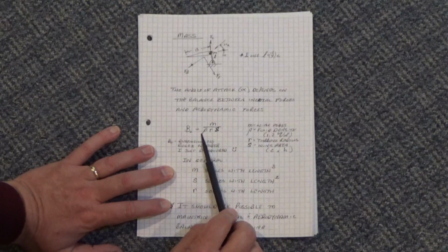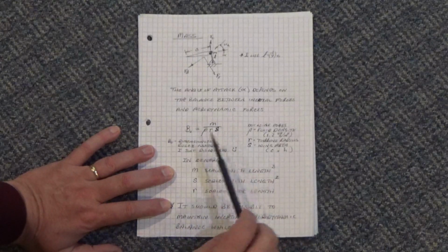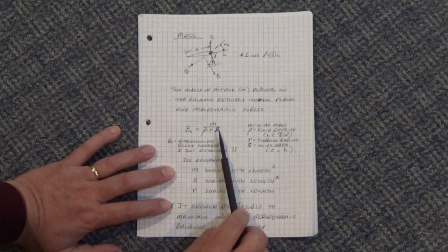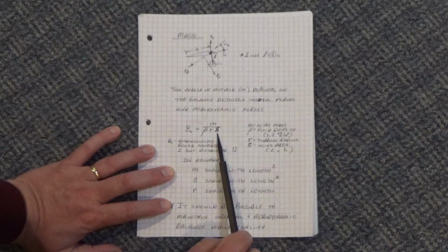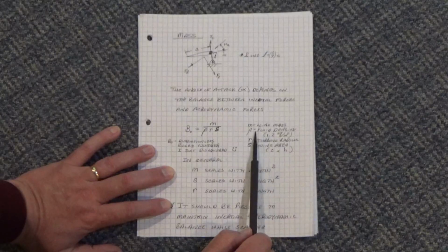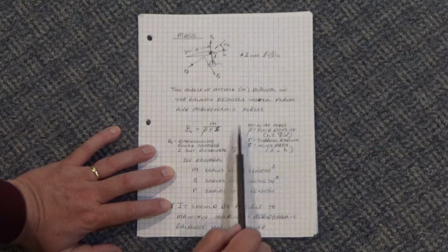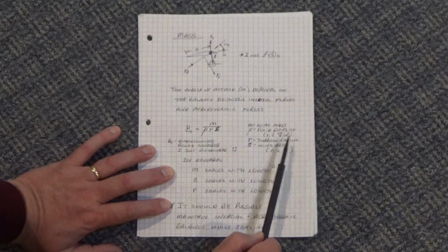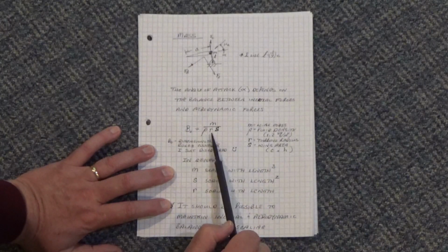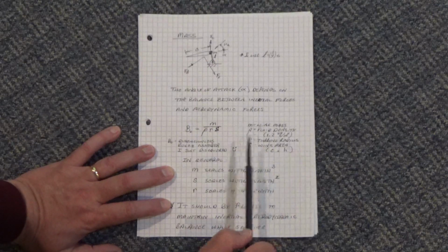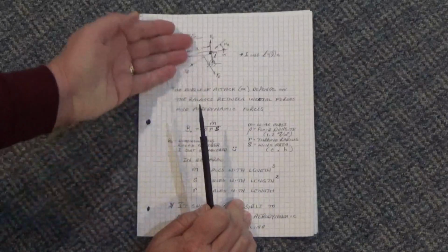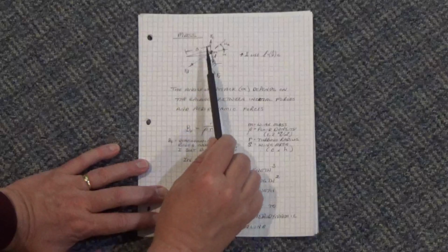And then I've got the fluid density, because the forces will vary with the density, and then you've got the area of the wing. I'm just calling it S here so it doesn't get confused with the area of the turbine. So usually with air, you've got the wing mass up on top, the fluid density, which is around 1.2 kilograms per meter cubed for air. This R is the radius of the turbine, and this S is the wing area, which is the chord times however high this wing is.